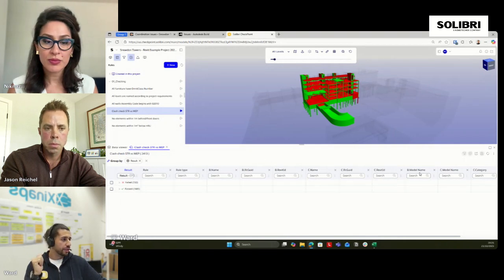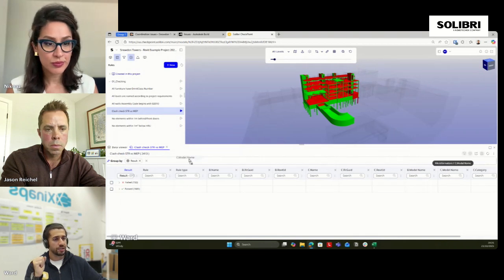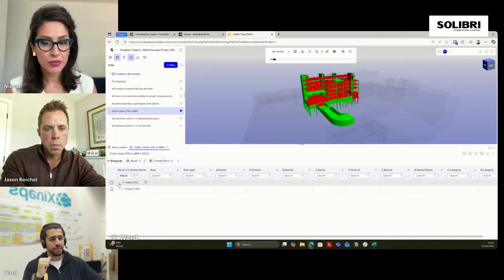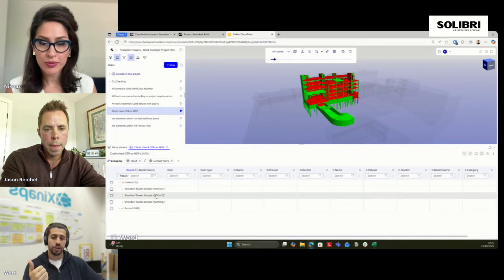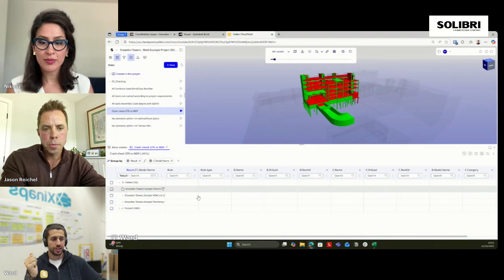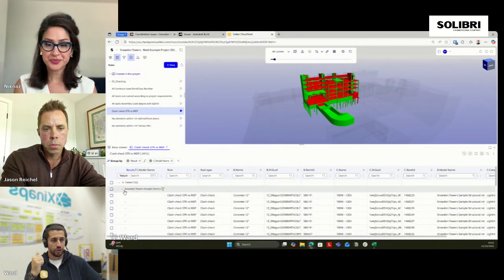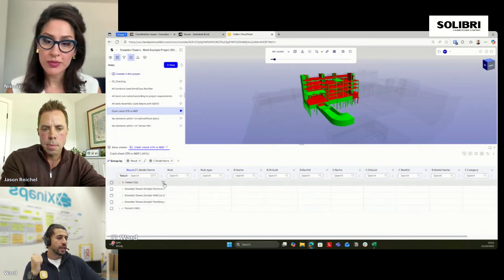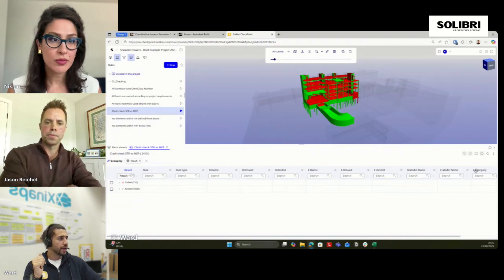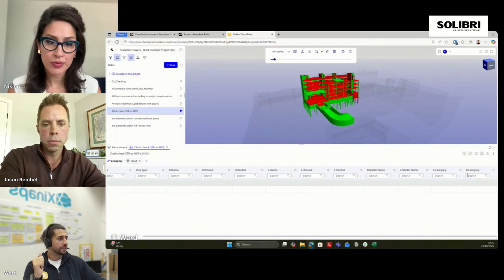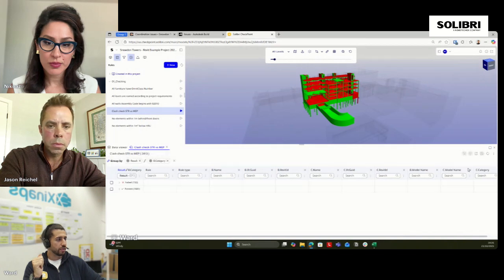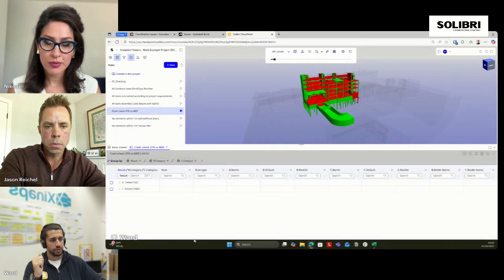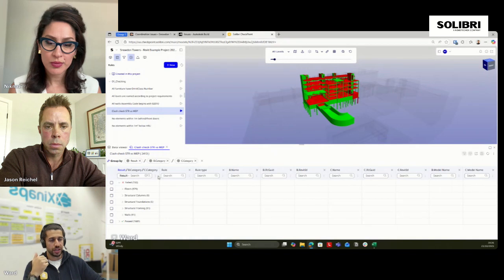So there you go. The first type of grouping that I can do is a simple grouping. I can add the colliding elements model name. In this case, I will see in the failed section which models are clashing over here and the number of clashes in every one. Here we have the electrical clashes. This long list is for all the electrical elements that have intersections with the structural ones, and the same thing for the rest of the MEP models. Another way of grouping them would be by adding the base and colliding elements categories. So I'm going to add another property by which I want to group the elements, and there you go.